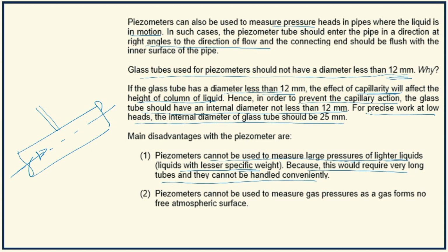Then the second disadvantage is that piezometers cannot be used to measure gas pressure. You can use piezometers only for measuring liquid pressures. You cannot use piezometers for measuring gas pressures because a gas does not form a free surface.